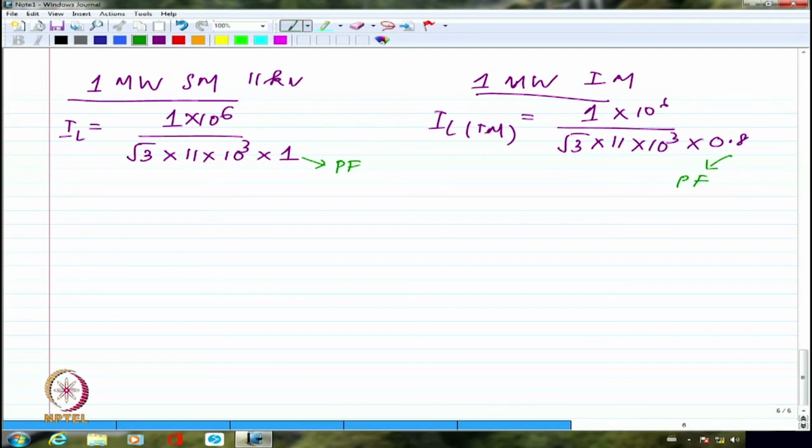So we are going to generally see that wherever very large capacity applications are concerned, where I am extremely concerned about the efficiency, synchronous machines generally are the first choice. But if I don't care so much about the efficiency, but I am worried about the initial installation cost, I'll rather employ an induction machine.